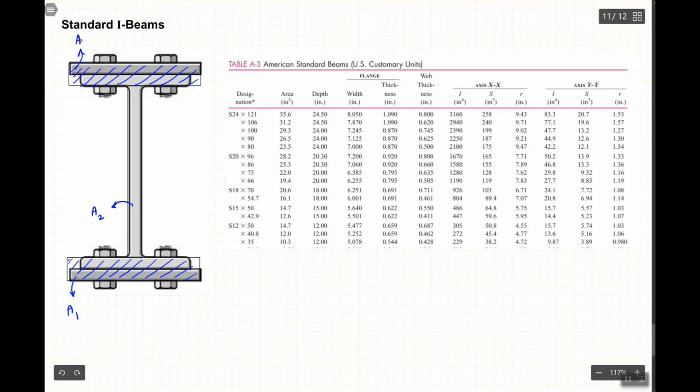And then based on the size that we have for this beam, we start calculating the moment of inertia and so on, similar to what we did in the previous example, right? But it's a tedious job, and there are tables that provide us with information which we can use to find the moment of inertia. For example, when we go to the market to buy an I-beam, we realize the I-beams have a code.